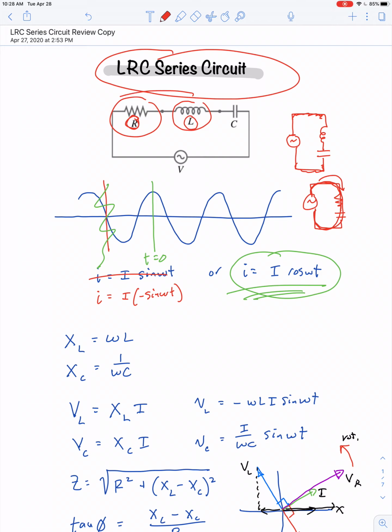So the bottom line is you can't really avoid these quantities in electric circuits. So knowing how they behave when powered by generators or by sources of AC is important, because this is how we power all of our homes and businesses. The reason we choose to power with AC instead of DC is AC's ability to be transformed. We can step voltages way up at power plants and step them back down at the house, and therefore avoid energy loss in the transmission lines by transmitting the electricity at high voltage and low current. So there you have it. We'll do a couple more example problems to try to illuminate what all these equations mean.